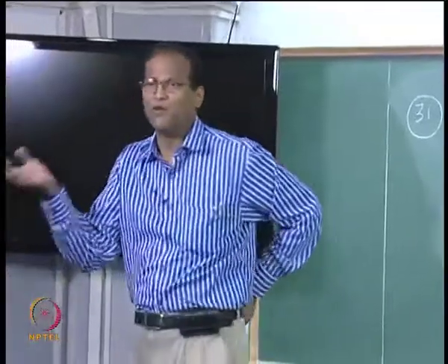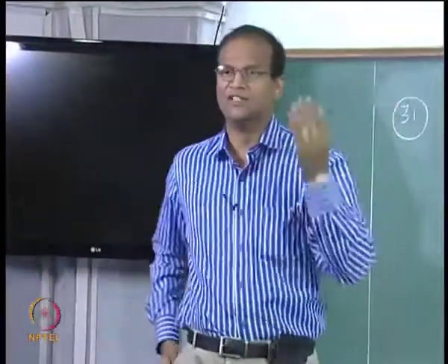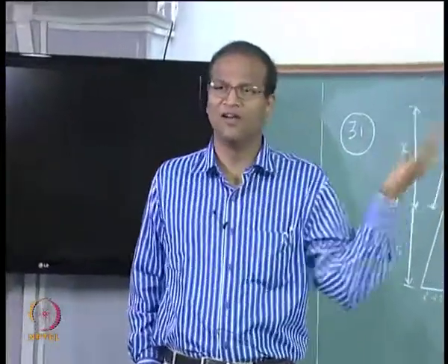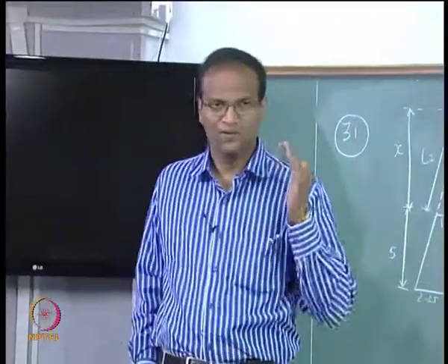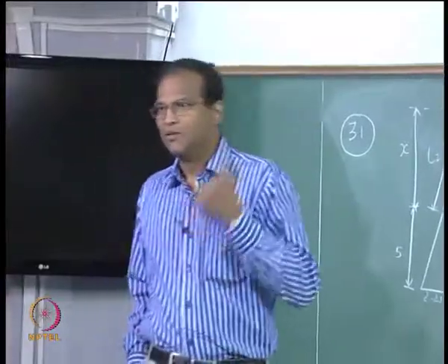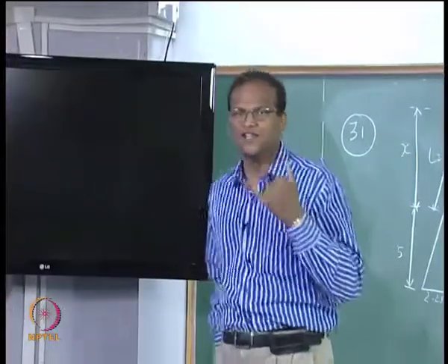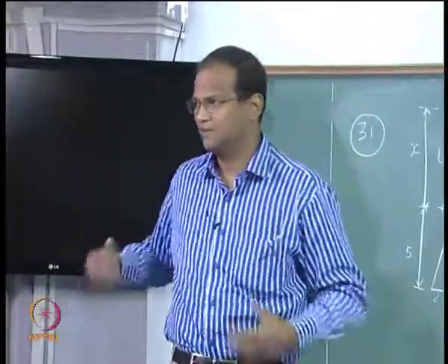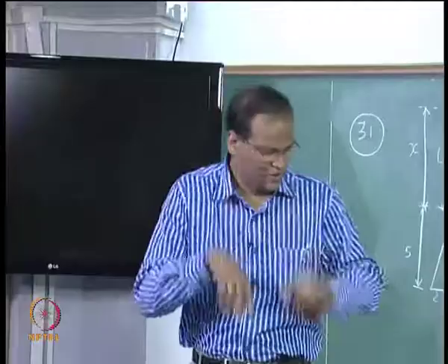Even though it is T to the power of 4, which you think is non-linear, convection, with u dou T by dou x or u dou E by dou x, is terribly non-linear compared to this, because it is very direction dependent. If it is a recirculating flow, if the direction changes, then the u, v all that will struggle to converge. So we will stop.